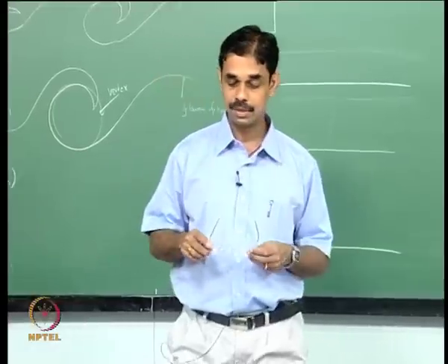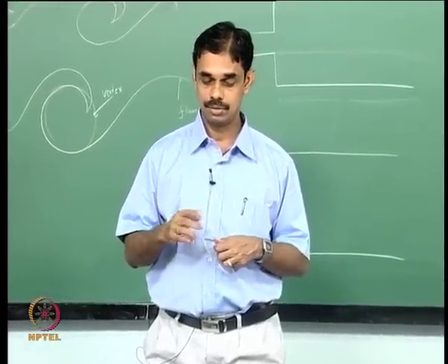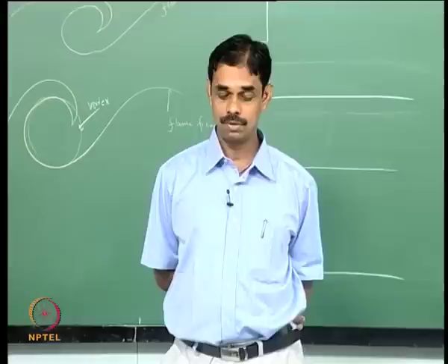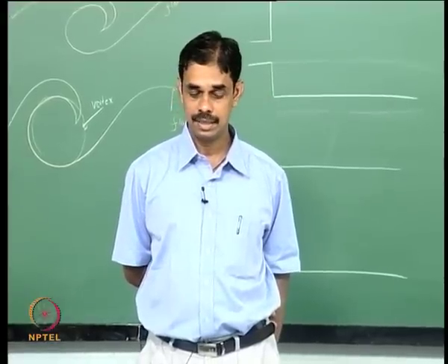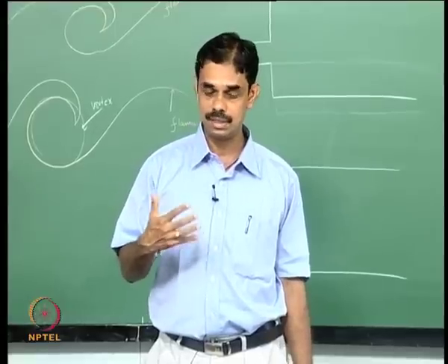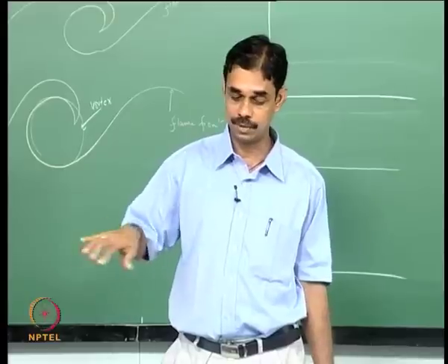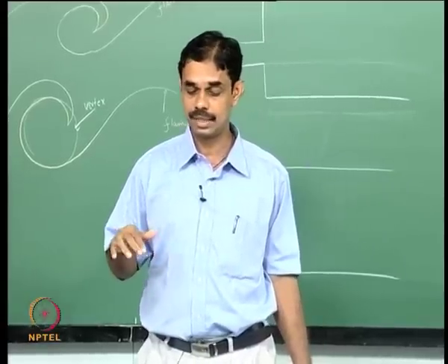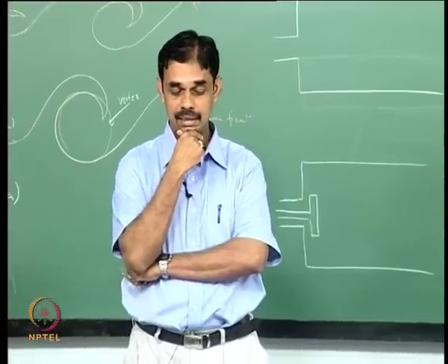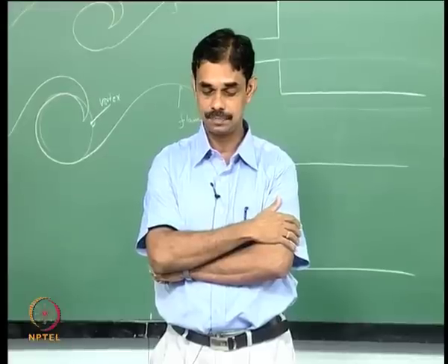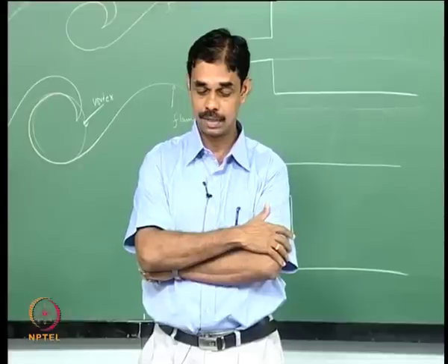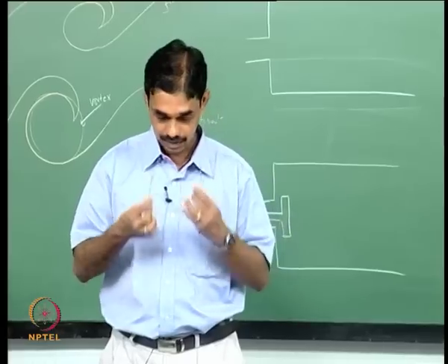So based on laboratory experiments with low Reynolds number, so this is a fluid mechanics experiment, not really combustion, low Reynolds number experiments of turbulent flow, it was shown that the shear layer initially develops instability waves in the initial region, and then when these waves reach a certain energy level, they roll up into vortices, and so there will be an initial vortex shedding frequency, let's call it Fi, which is also the most amplified frequency, and it is often determined by characteristics such as the shape of the velocity profile, turbulence in the profile, initial shear layer momentum thickness, and the jet exit velocity.